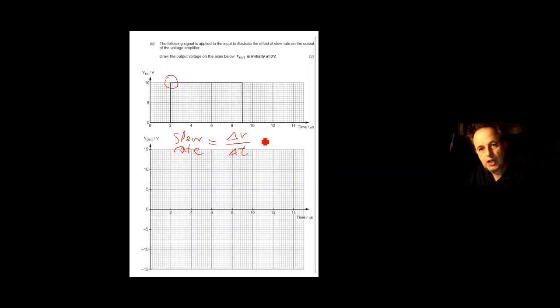Now in this case, it would be trying to change 13 volts. Got 10 volts going in, gain is 30, it would be trying to give you 300 volts, can't, gives you your saturation. So it's going to try and change 13 volts.